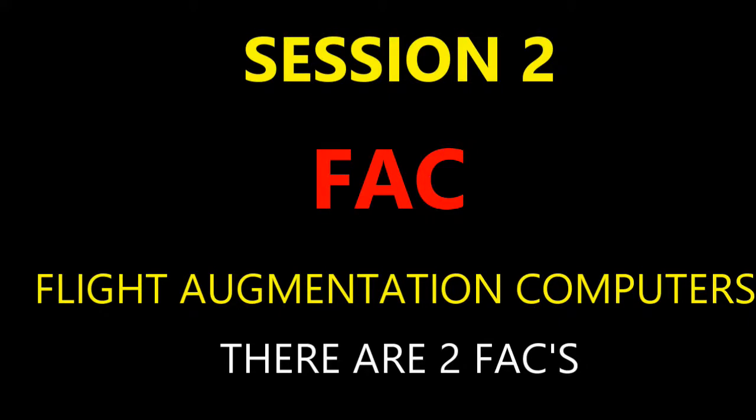Now, what about the land mode? You have a land mode. When that's engaged, then you have the yaw order that's computed directly by the FMGCs. Okay, that's the next thing we're going to talk about in session 3, but just that's the connection. Here's land mode connected because it's computed directly by the FMGC.